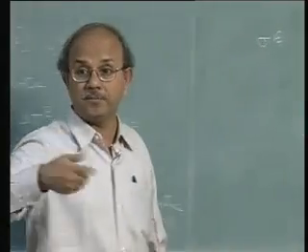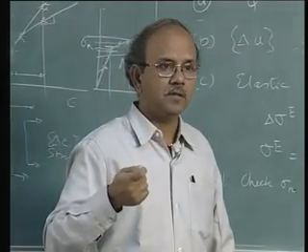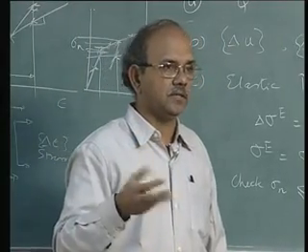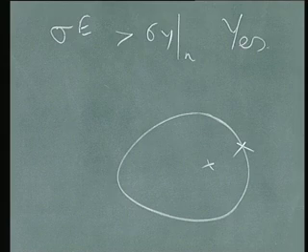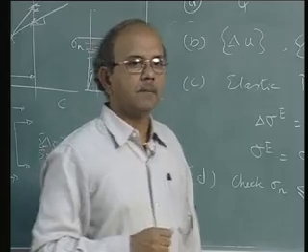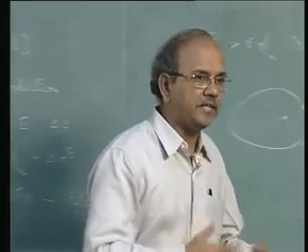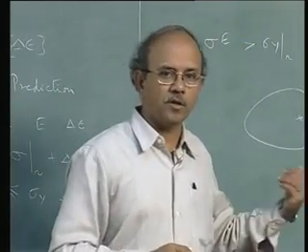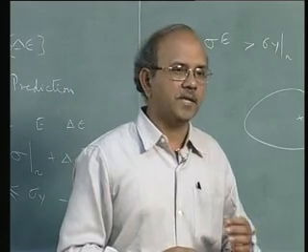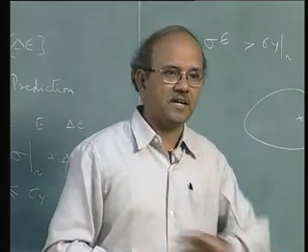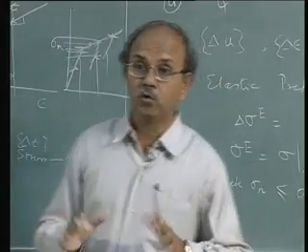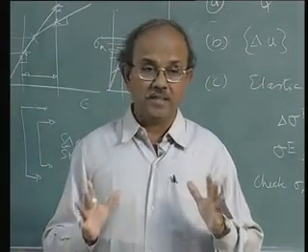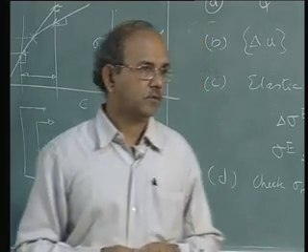I am introducing a lot of terms as I explain. Note these terms. I said history dependency, in other words, the stress or the strain depends upon the history, and I now used a term called rate independent. In other words, the behavior that we are right now seeing is a behavior where strain rates have no role to play. It is only the plastic strains which have a role to play.